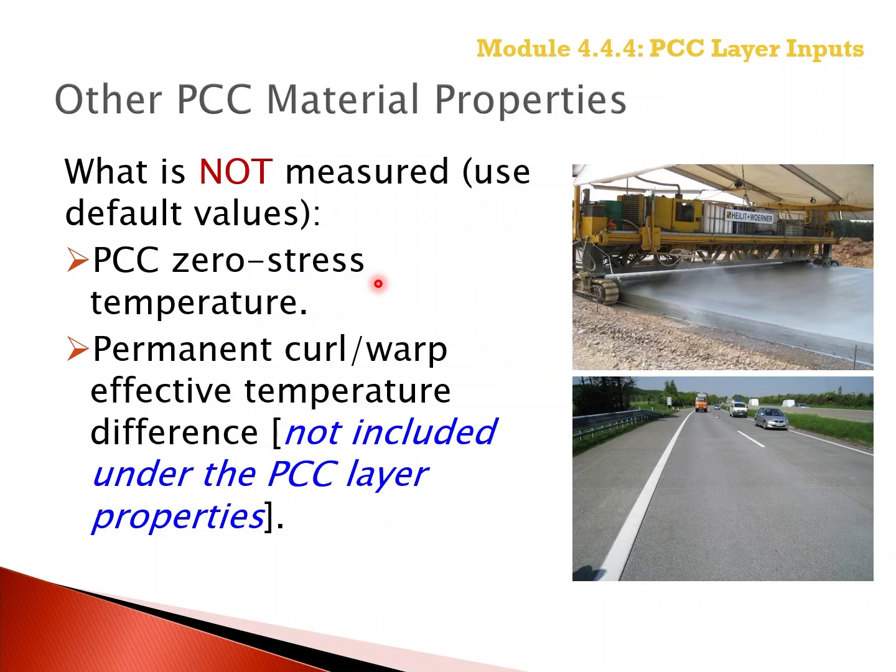The temperature value is normally calculated using the regression equation in the PCC software, but it can also be entered by the designer. The variables included in the regression equation that impact the PCC zero stress temperature are the mean monthly temperature for the month of construction and the cementitious content of the concrete mixture itself.